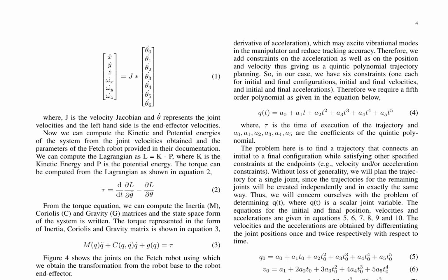Trajectory planning for the manipulator involves point-to-point motion for each of the 7 joints, subject to position, velocity, and acceleration constraints to avoid discontinuities in acceleration, which can lead to impulsive jerk and reduce tracking accuracy.